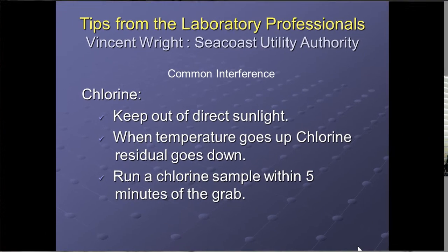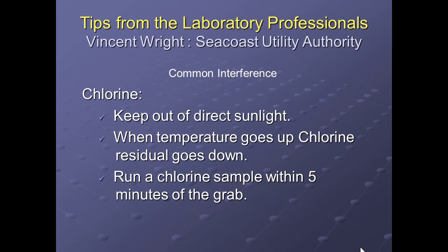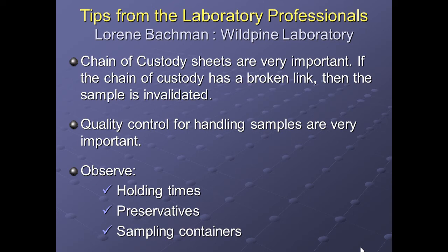Vinny, on the chlorine interference, says that chlorine and direct sunlight are going to affect it. As temperature goes up, chlorine residual goes down. Run the chlorine sample within 5 minutes of the grab, and we mentioned that in the beginning of our presentation, which was video 1.